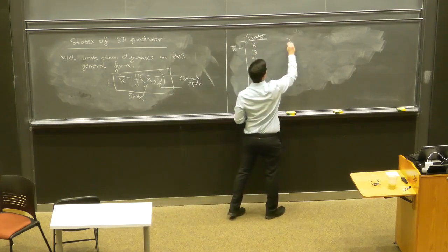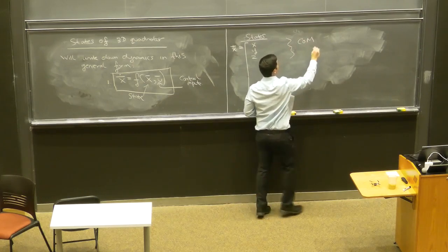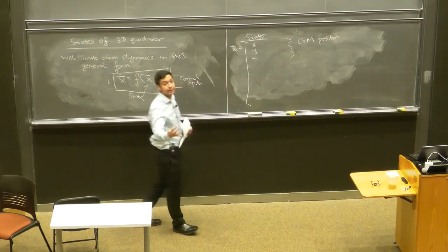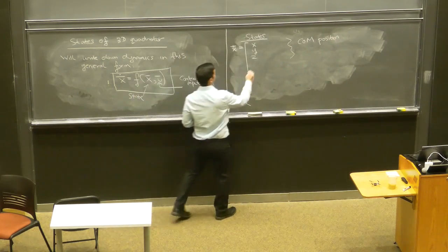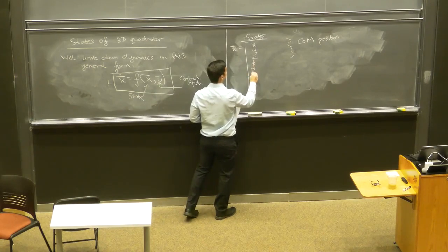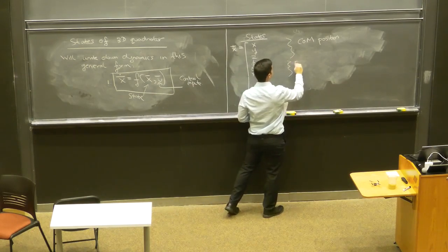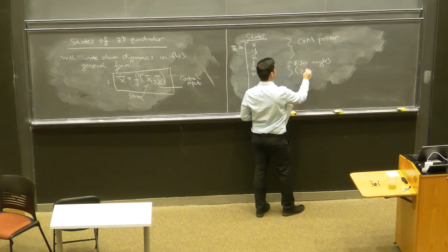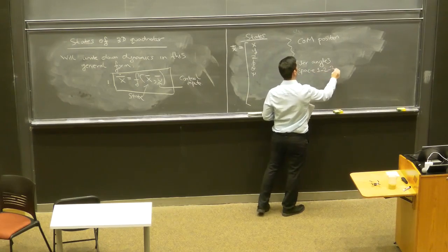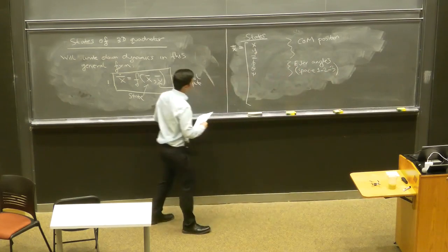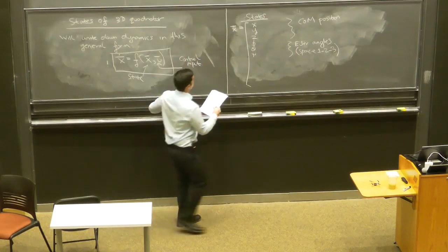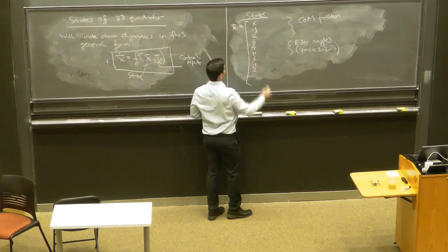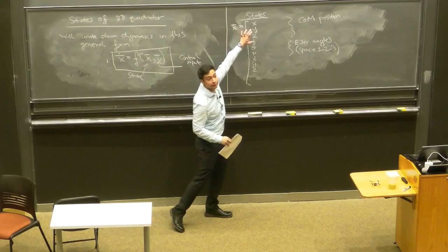This is the center of mass, COM position. These are the variables that correspond to the translational degrees of freedom. Phi, theta, psi. These are the Euler angles, again using the space 1, 2, 3 convention. So these are the first 6. And then we're going to have x dot, y dot, z dot. Those are the time derivatives of the positions.